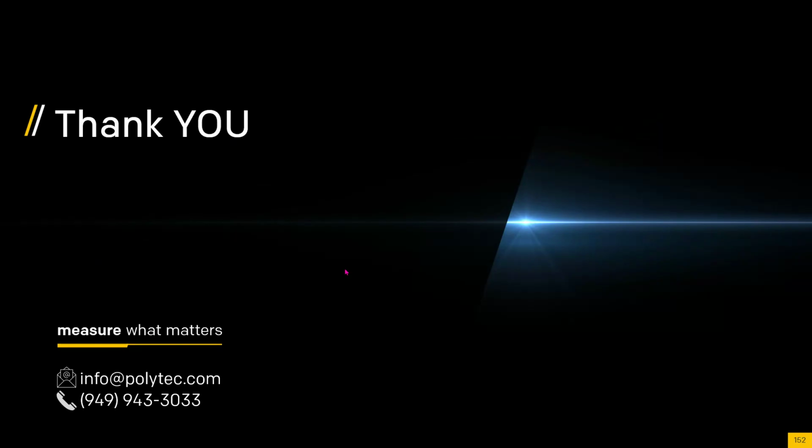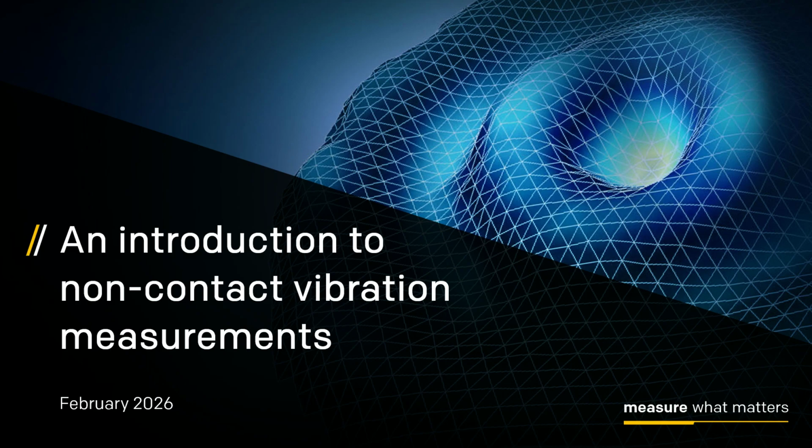The first question I have here is, what is the minimum and maximum frequency and amplitude a vibrometer system can handle? So we have customers and applications going all the way from DC to 8 gigahertz, and we have people asking for higher now. It could be micro positioning stages, nano positioning stages, which are DC or quasi-DC. And the high end is 8 gigahertz for now.